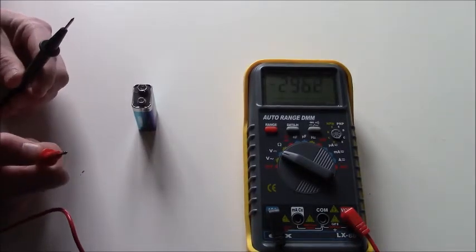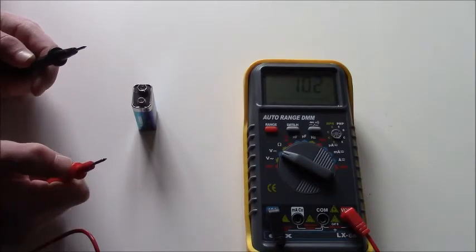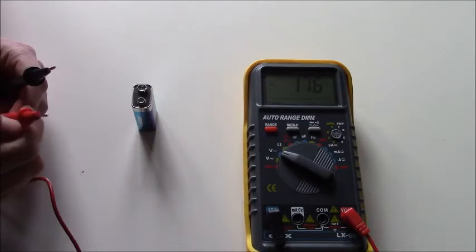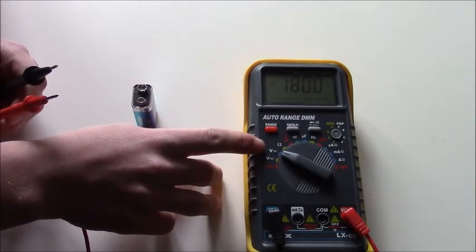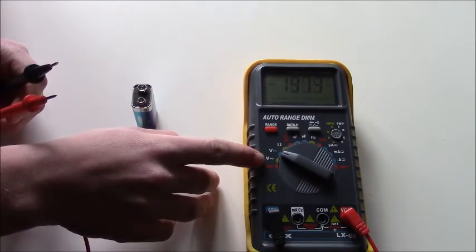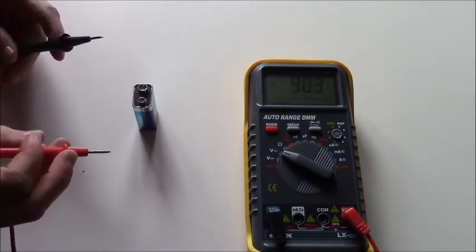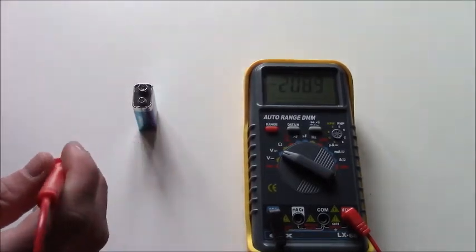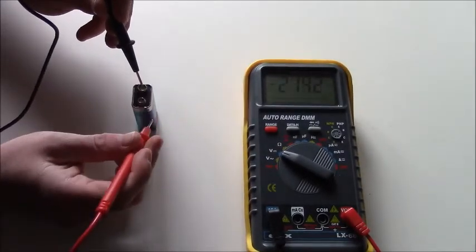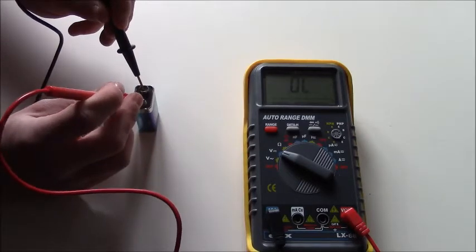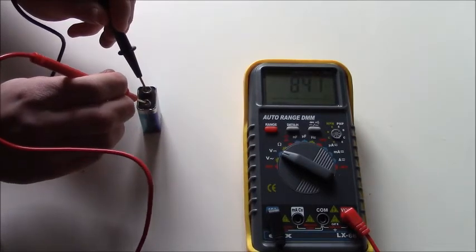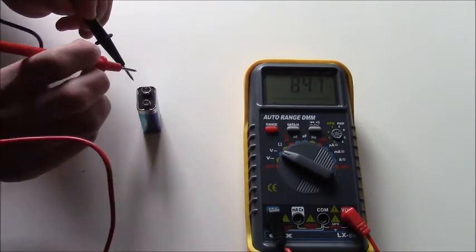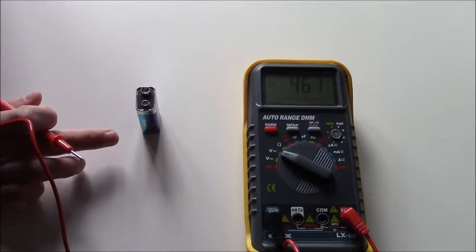If you want to measure the voltage of a power source, you first have to know if it's AC or DC. A battery is DC. So, for this, we're going to turn on DC. If you have an AC power source, you turn on AC. To measure the voltage of the power source, you put the two pins on the two terminals of the power source. So, for example, you put the black one on the left and the red one on the right, and you can see you get a positive reading of 8.40 volts in this battery. This means this battery has 8.40 volts.